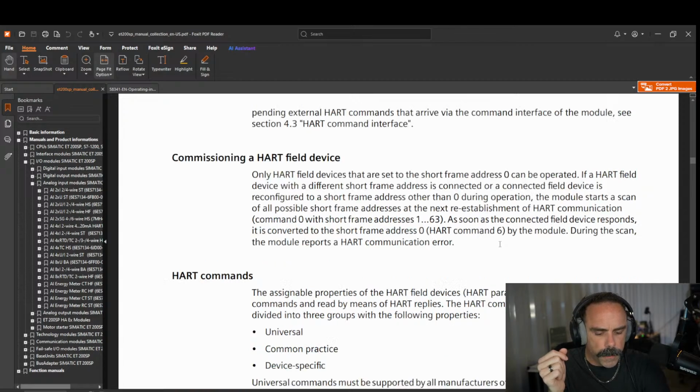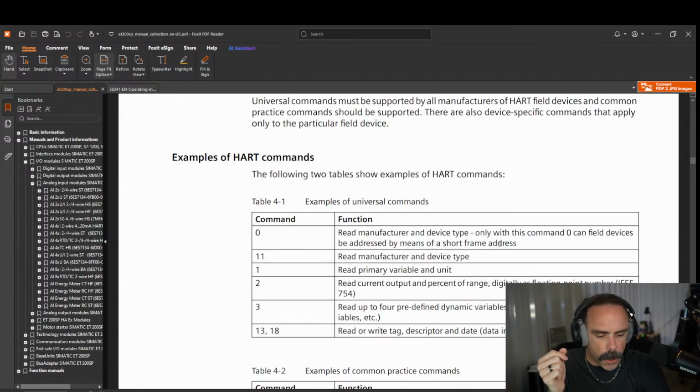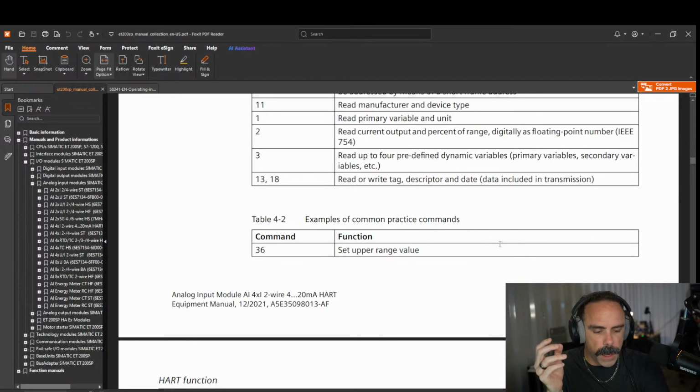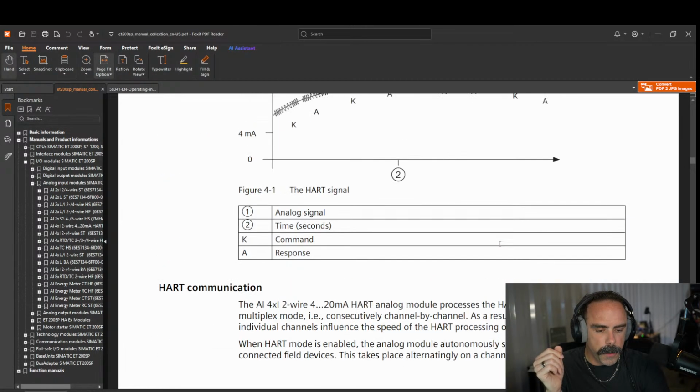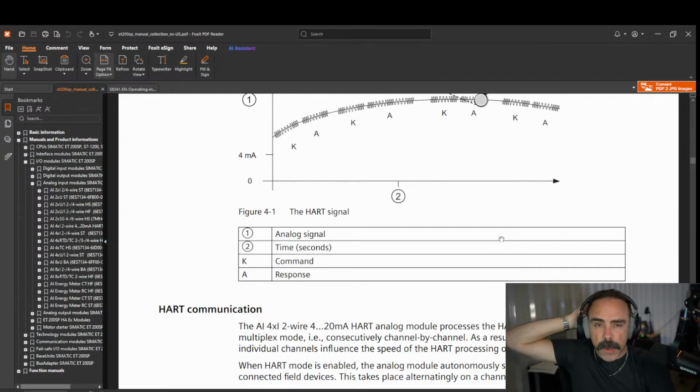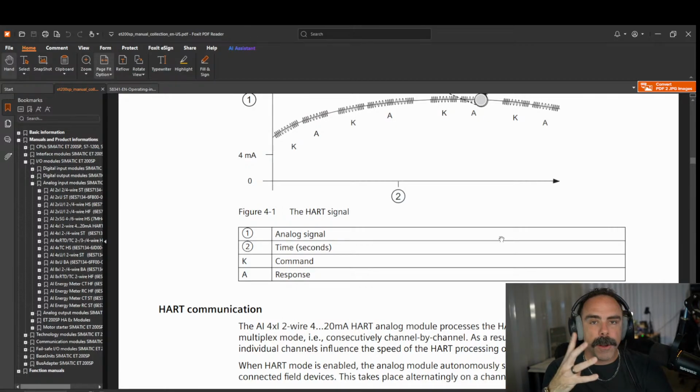So one of the things about HART is that it is pretty configurable, and we'll go through it. Most HART, by definition, I say most, it is by the definition, you get 4 variables. And yeah, so Nathan, it is very much like FM radio. It is taking off that modulation, that frequency modulation, and pulling out digital signals.